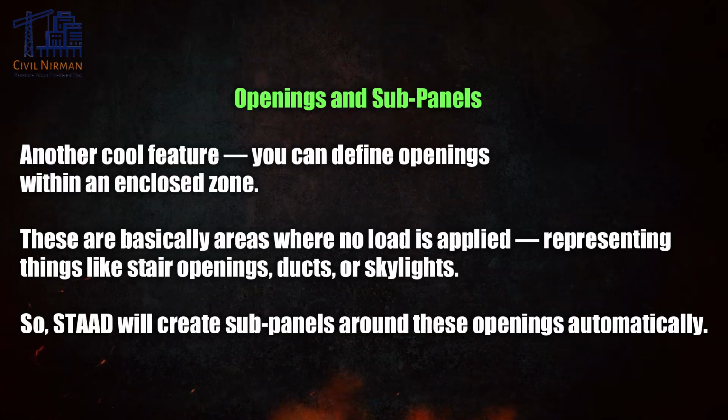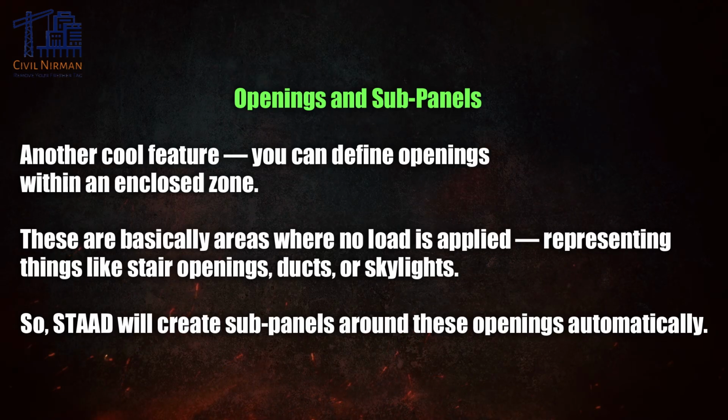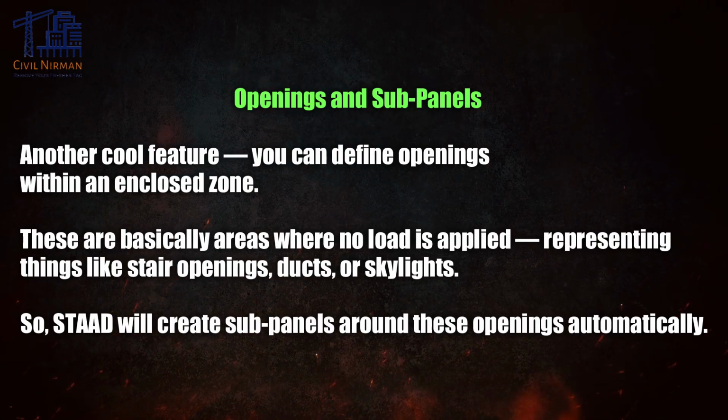Next important part, openings and subpanels. This is another cool feature. You can define openings within an enclosed zone. These are basically areas where no load is applied, representing things like stair openings, ducts or skylights. So STAAD will create subpanels around these openings automatically.